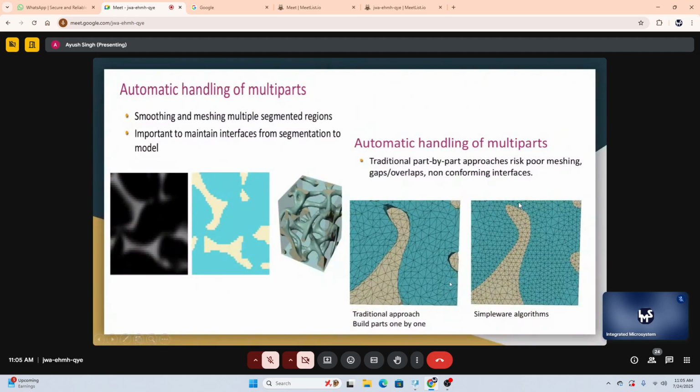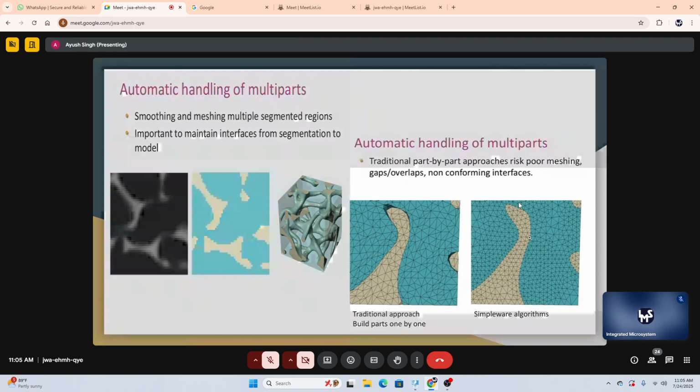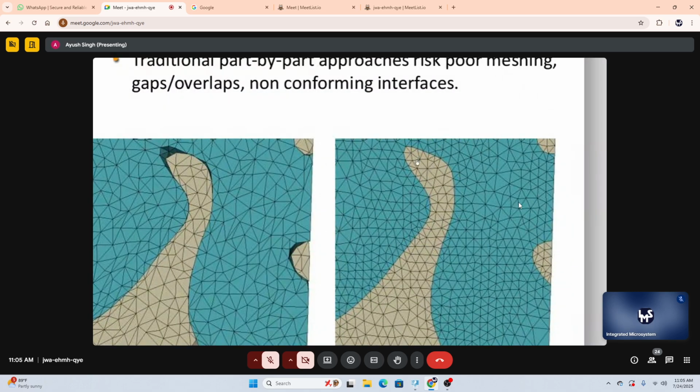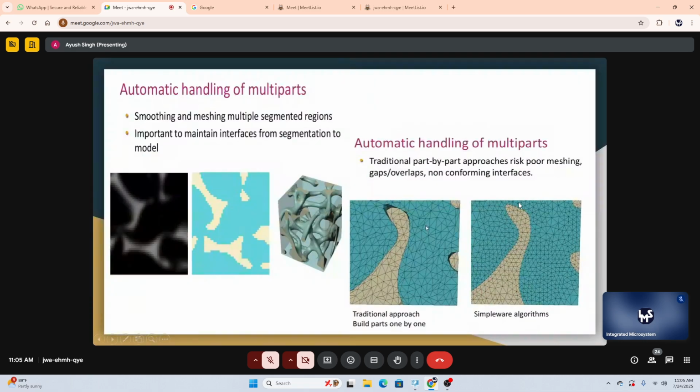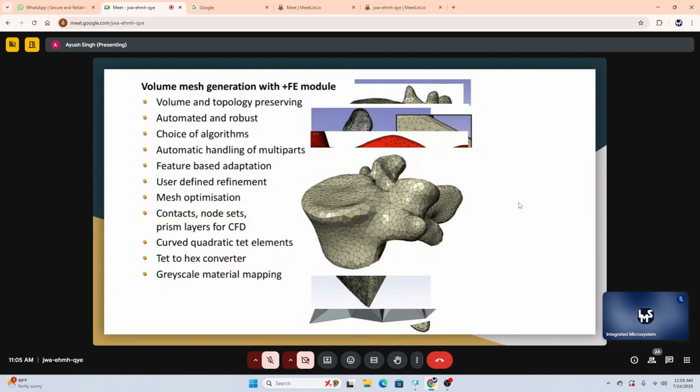So we have two sets of approaches to convert this data into accurate FE models. We can use an FE model tab to accurately define the boundaries and increase the mesh size and mesh fineness over those points, also accompanied by the contact pairs and the node sets that we need to use. When we increase such values, it ultimately results in a high-value output, and the accuracy is quite good.